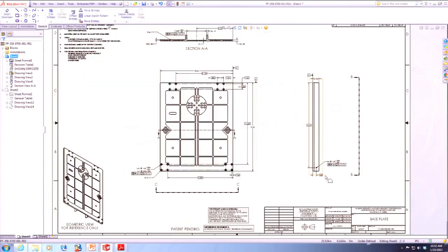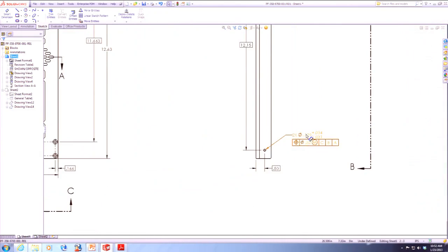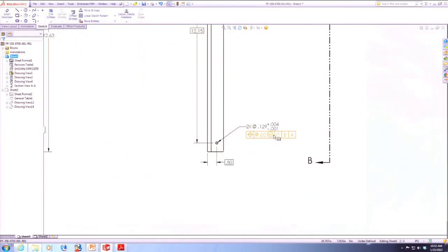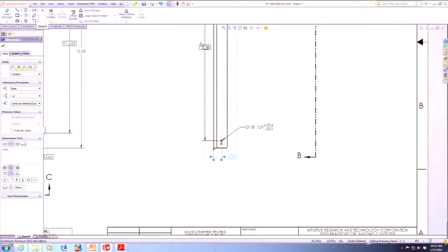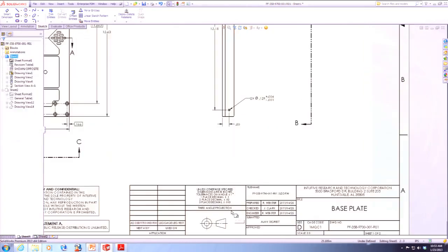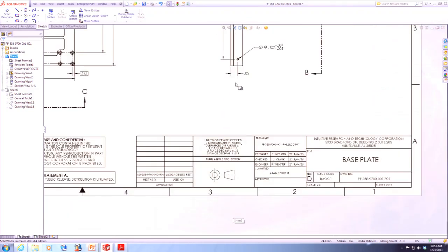I think we all know it, but if we focus on one small little hole here, you can see that currently we've got our basic dimensions locating it. A geometric control frame applies the tolerance. That's GD&T, that's one way. Other ways available in SolidWorks are very simple. Standard locating dimensions with no tolerancing on them, therefore we go to the block tolerance. What's your tolerance?